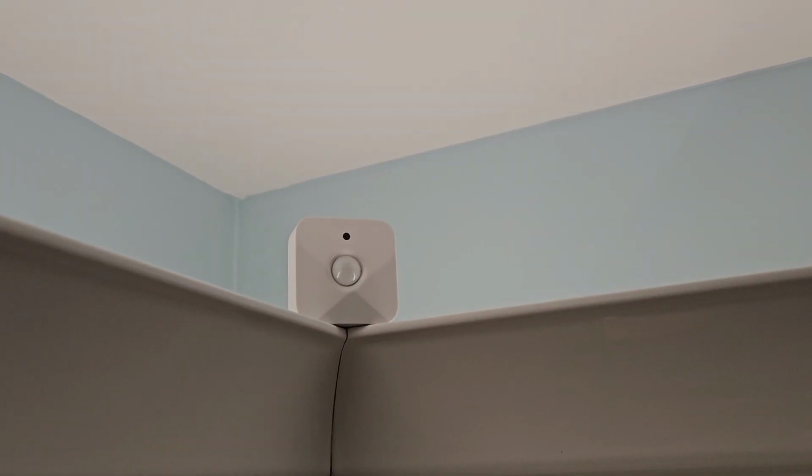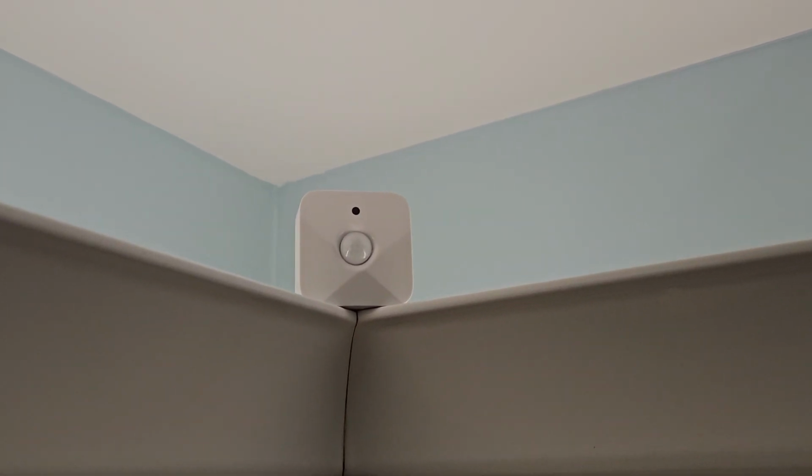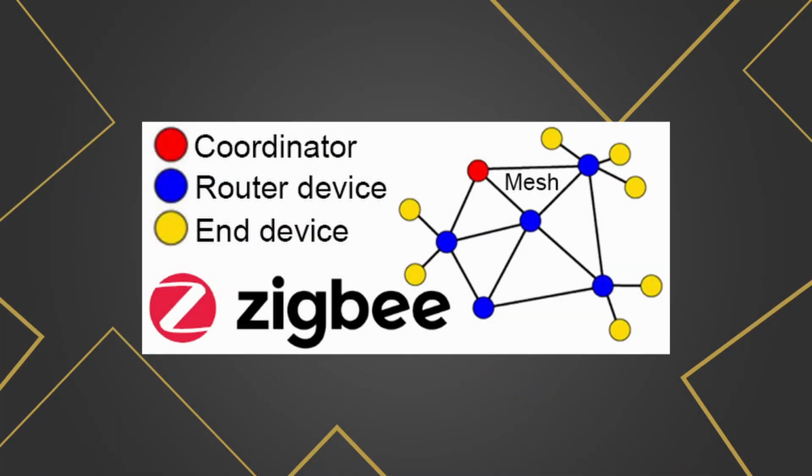Now, the other type of device within a ZigBee network is the end device, and these are battery-powered devices that are usually motion sensors or contact sensors, and these devices cannot act as routers. So other devices in a ZigBee network can't go through your motion sensor to get back to the coordinator because they are an end device and they run on battery. Okay, you must use a router which is mains powered, such as smart plugs and smart bulbs, and they will strengthen your ZigBee network and they will allow your end devices to get to the coordinator if they're a little bit too far away.